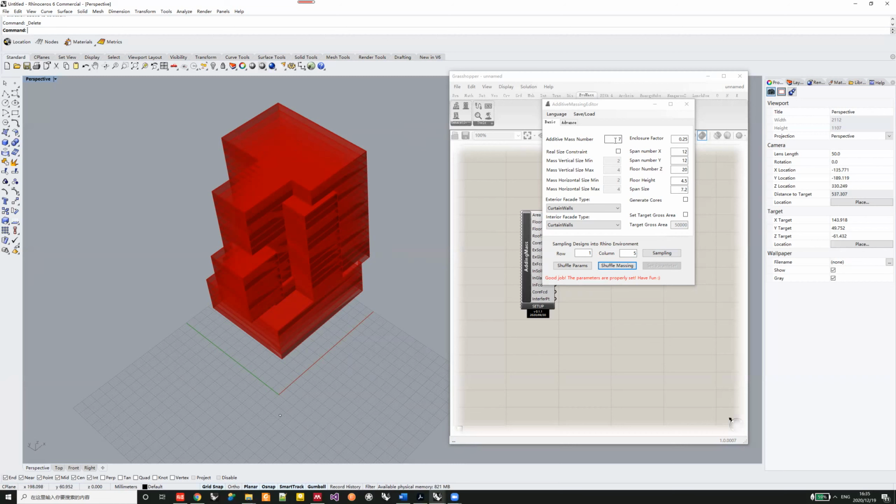So if there are 7 unit meshes, it means there will be 42 parameters. If the number of parameters is too large, it will cause trouble for the optimization algorithm to search for the optimal solution. So be aware of the number. And if you're using such a large number of unit meshes, you may need to increase the number of iterations in the optimization algorithm.